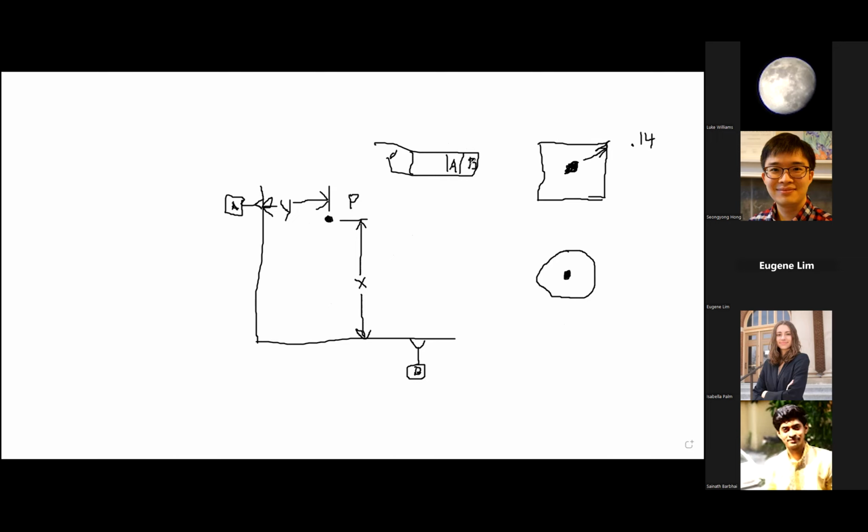So we are going to control this location. And this first cell shows the location symbol. And we're going to control this location using a 0.1 tolerance. And then we're going to have a leader line that points to our feature, whether this is a point or a hole or what have you. Now, using this control feature,